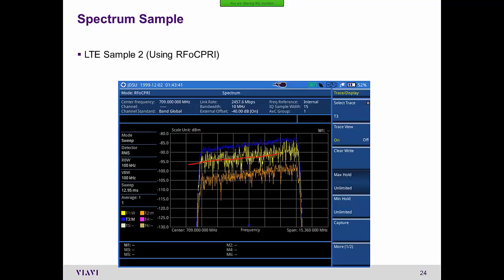Here's another. This is a really bad example, and you can see the slant's pretty clear. You can see it very distinctly in the max hold here at the top. But really, this slant never gets any worse. The actual signal, once the PIM was fixed, should have been down here at the bottom of the display. But what you'll notice is it slants and rises.